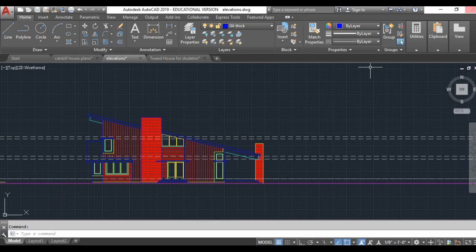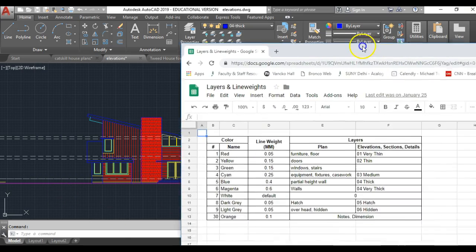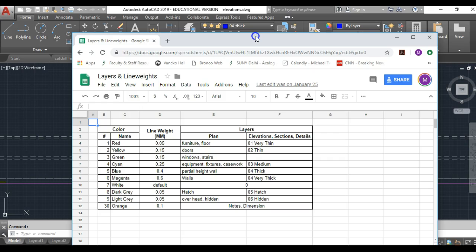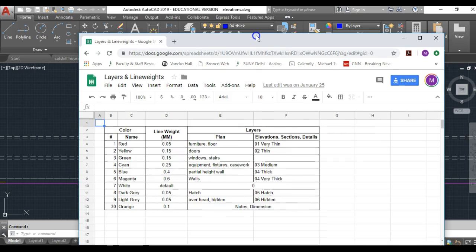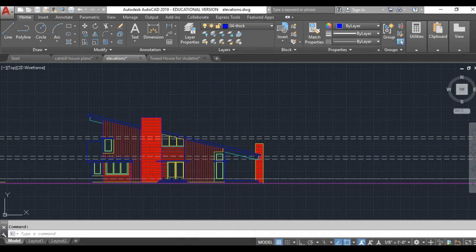And if you remember from my standard that I had shown in the last video, which I can put up briefly here, if you need to pause it, you can take a look in this video. But I have it set up so my thickest line weight is magenta, my lightest is red, and the steps in between in that color plane in the AutoCAD layers continually increase. So my cut line elevation's got one, it's this.